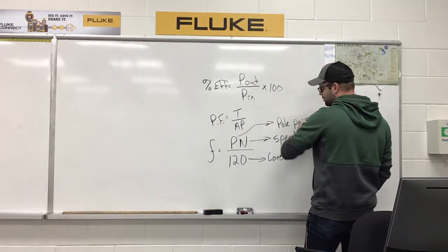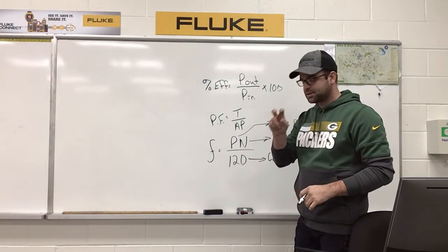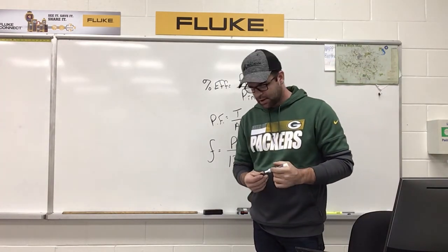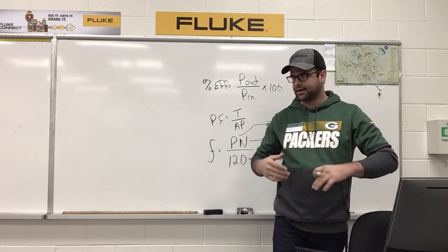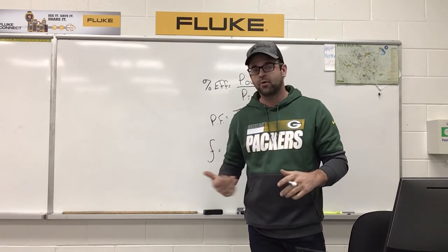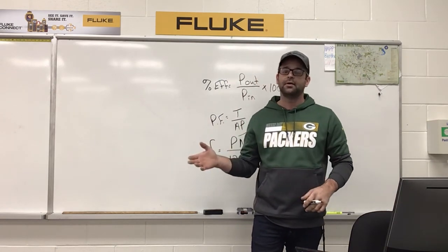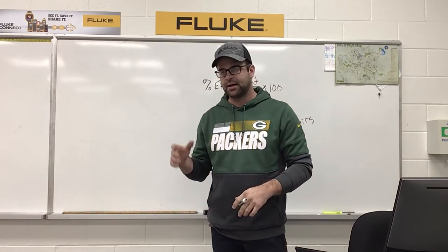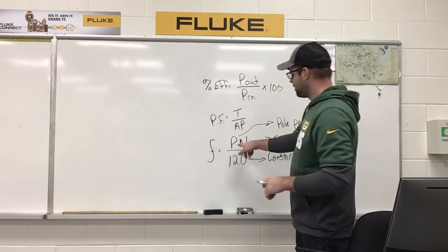And just remember with this too, when I say pole pairs, obviously that means a pair, meaning 2 inside an alternator, but if I ever write down a value for poles inside an alternator, let's say I give an answer of, oh, there are 10 poles in the alternator, I'm referring to pole pairs. I'm not asking you to do any math. I'm not asking you to take that value and divide it by 2 in order to get 5 pole pairs. If you do see it in a question, it just means that that is the value you're going to plug into the formula.